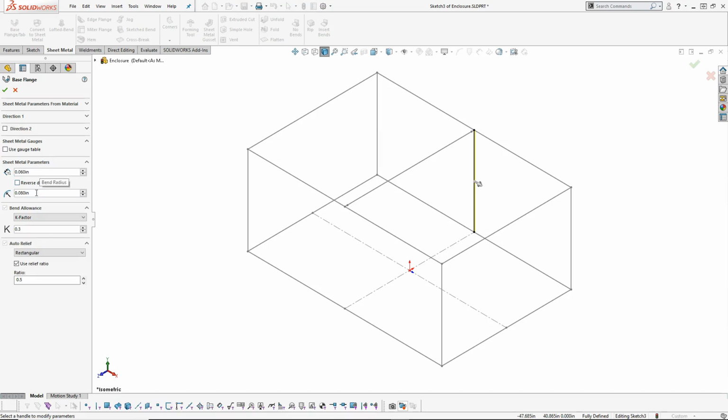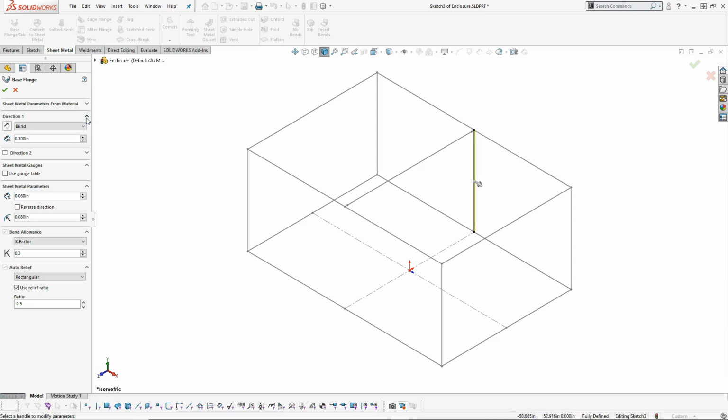We're not really doing any bends, I just want to manage these items, but 2 millimeters, 80 thousandths, is probably reasonable, with a K factor of 0.3. Because we're not doing the bends, we're not concerned with the K factor, but as we stress and deform the material, it allows it to grow as we make the bends, to account for that deformation.